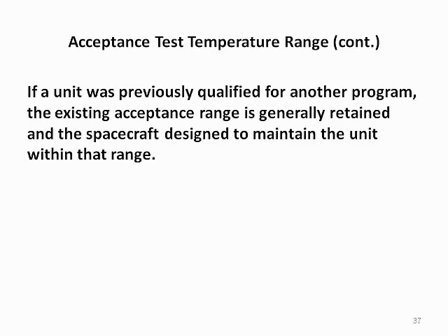If a unit was previously qualified for another program, the existing acceptance range is generally retained and the spacecraft designed to maintain the unit within that range. This is because requalifying the hardware is usually more expensive than tailoring the spacecraft thermal design to accommodate the existing unit allowable temperature range.